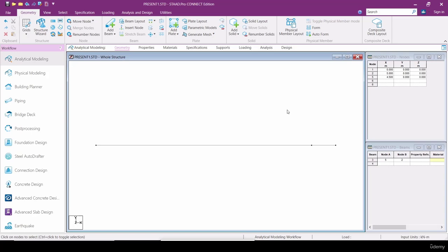You can copy any beam or paste any beam at a particular distance. That command also works here. And Shift N is a command to show the node numbers. If you click Shift N here, it shows the node numbers. If you see here, this is node 1, this is node 5, this is node 2. This command is for nodal numbers.